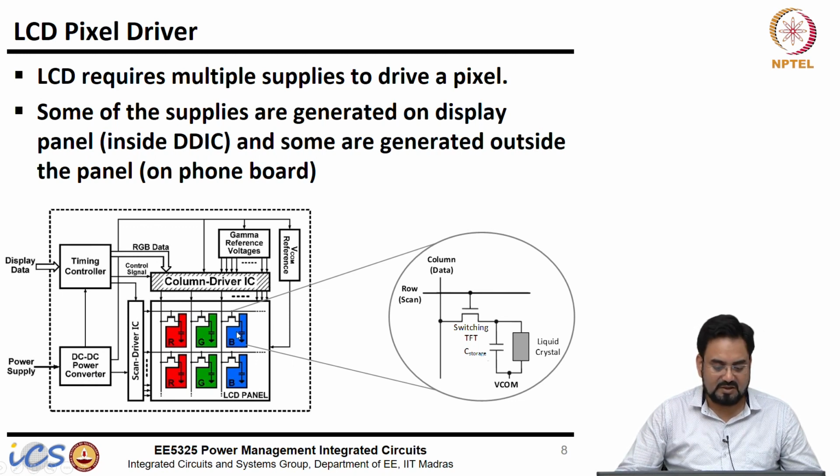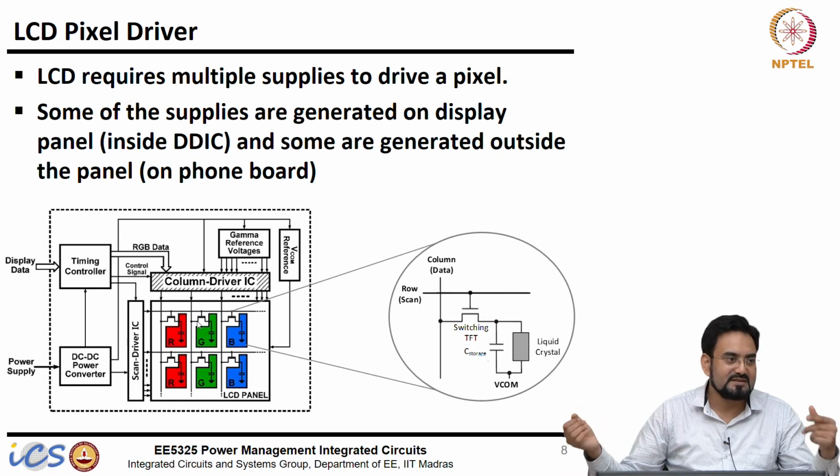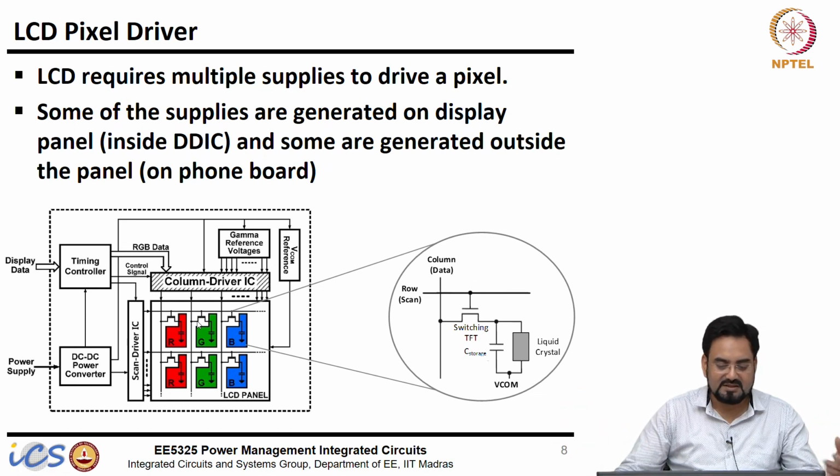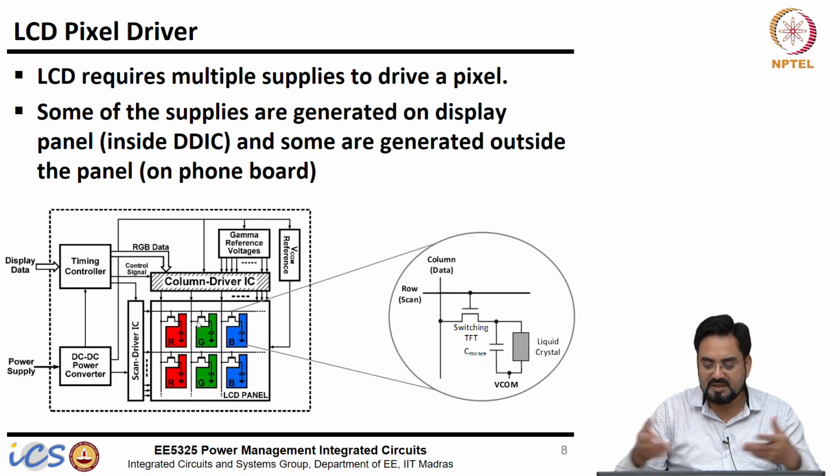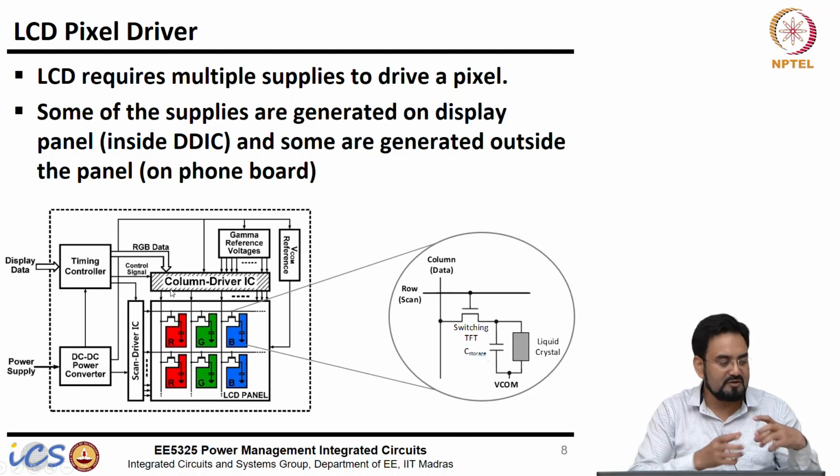So, it is a complex IC which is used for the display driver, and it has so many pins, because you can imagine you are driving a display with so many TFTs, and each TFT corresponds to one pixel. You know the number of pixels could be millions. So you can imagine how many columns and rows will be required. And most of the time this display driver IC is part of your panel.